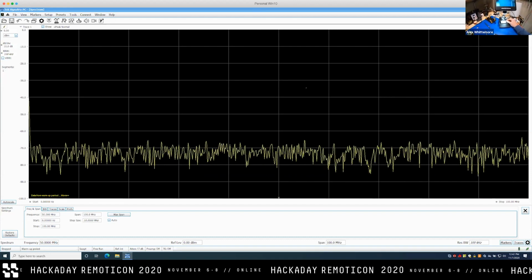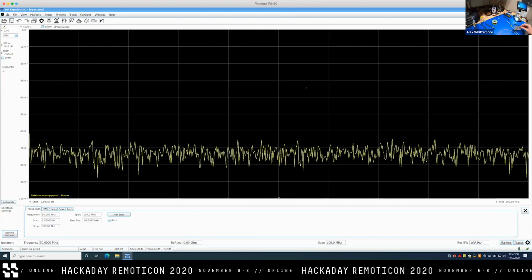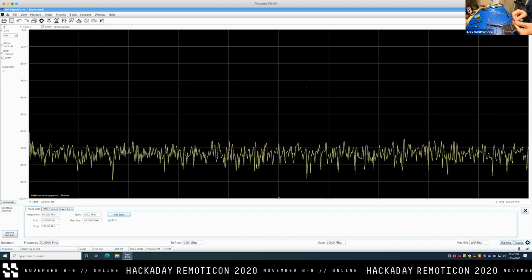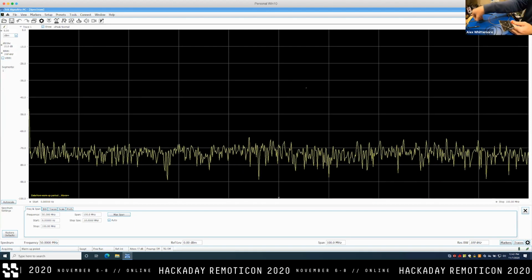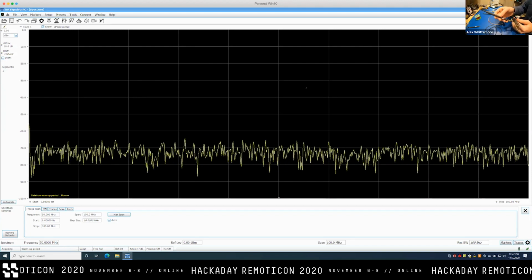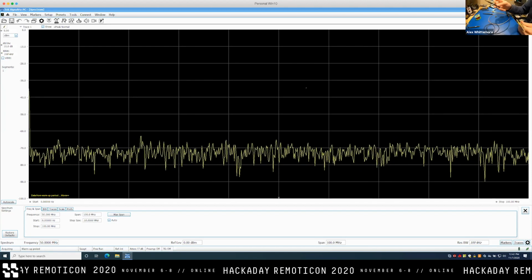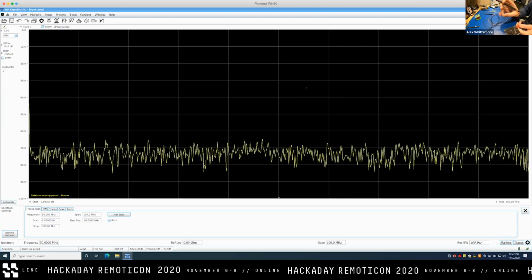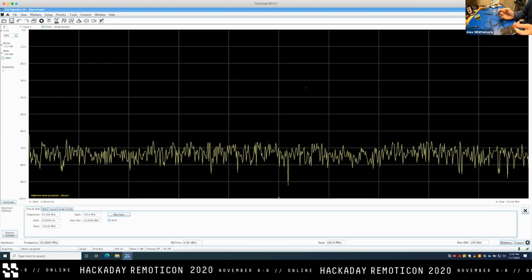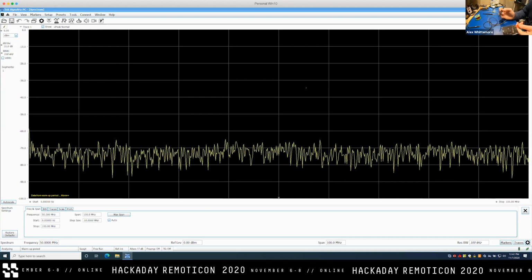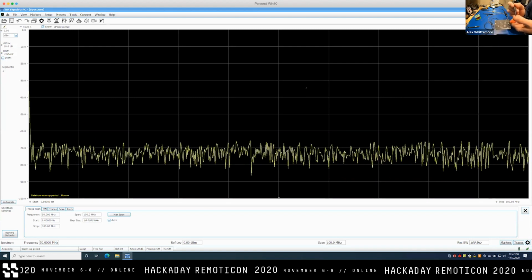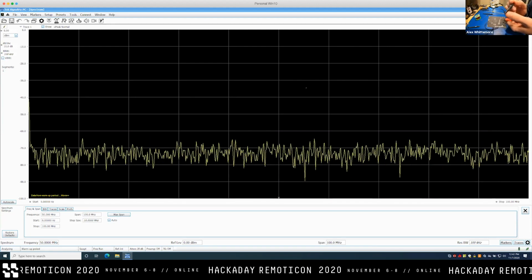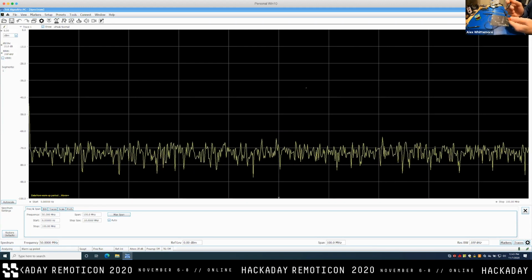And okay, what's going on over here? That's a little odd. Let's dig in on that a little bit before we get too much farther. I'm going to switch to this tiny, tiny little H-field probe. If this looks similar, for those of you who followed along at home to begin with the really small DIY probe you might have already made, the whole point of this probe is that it's the same magnetic loop antenna, but in a tiny, tiny little package up at that tip.